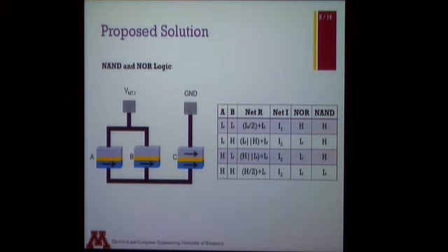The resistance in this particular circuit is here. So the first term is the parallel resistance of the input MTJs, and the second term is the preset low resistance of this output MTJ. So A and B are input, C is the output.